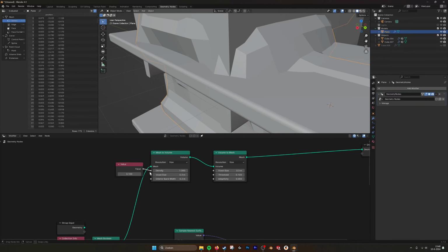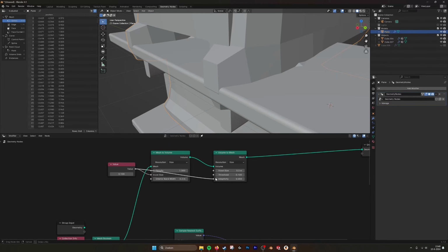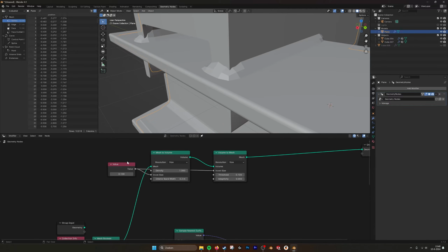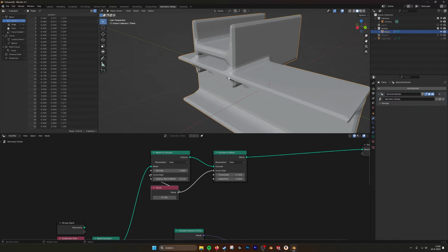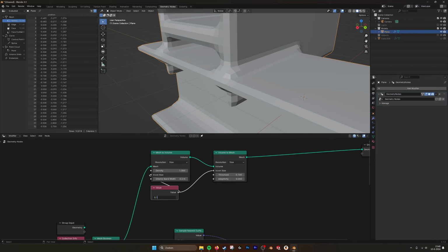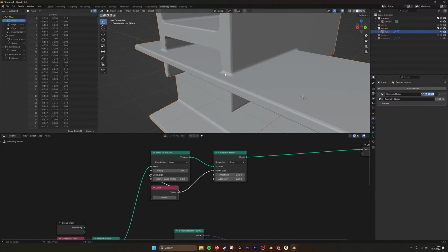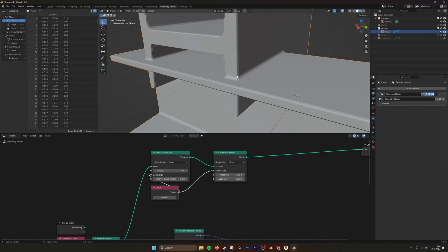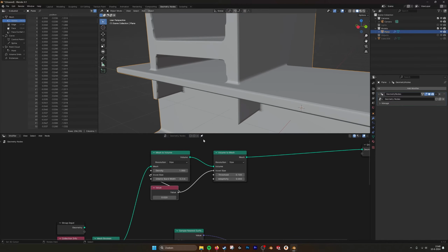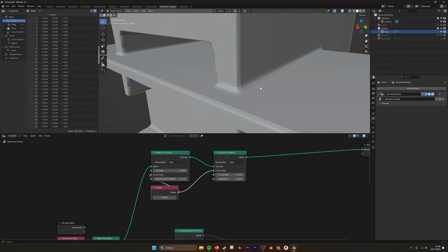We're going to tweak this, it's probably not 0.1, but if we do voxel size, let's turn this one off to see what happens. So this is quite rough. We need more resolution, so 0.2 maybe. And here now you see that this becomes smooth. So it's already looking a bit like a weld between the two parts. And this is what we need to calculate the right normal.